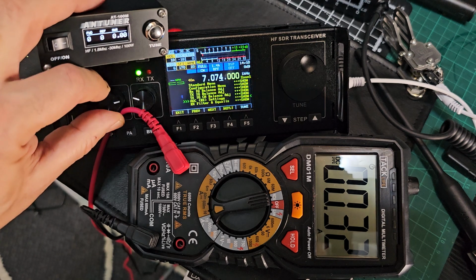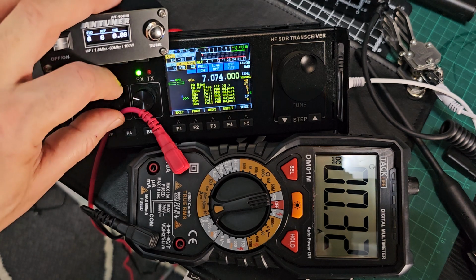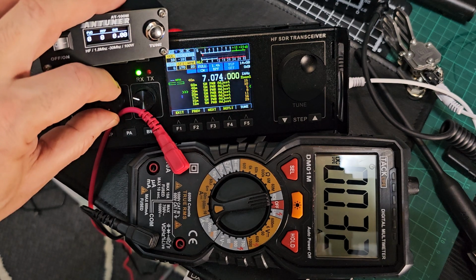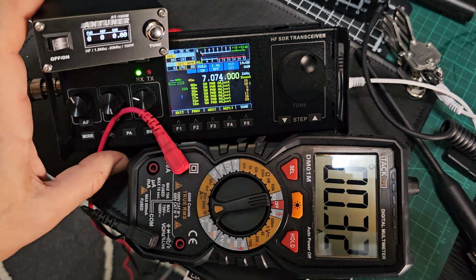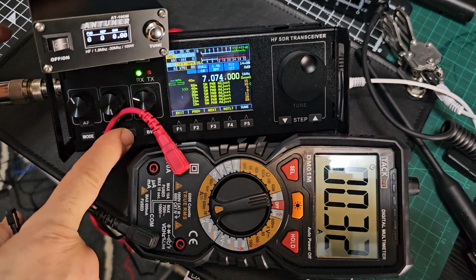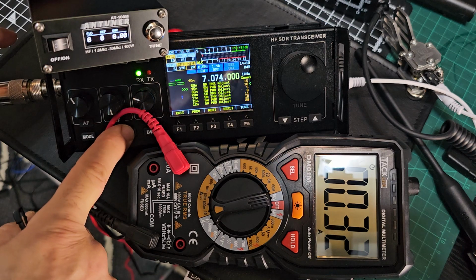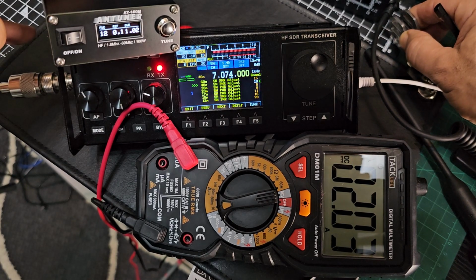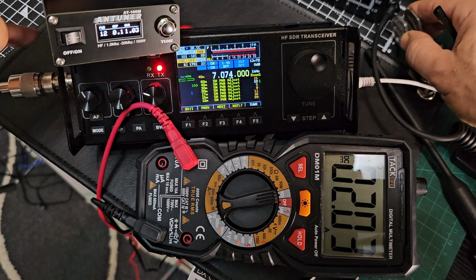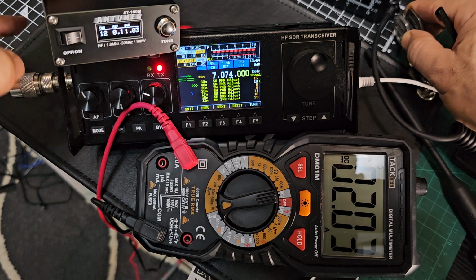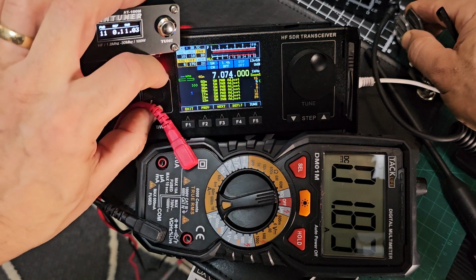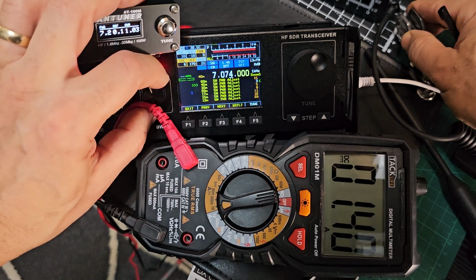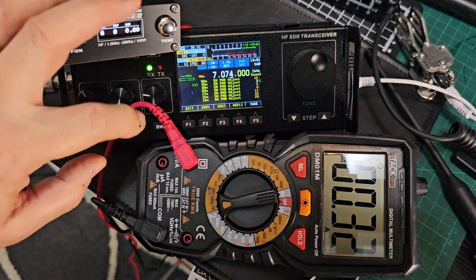Full power, where's the 5 watt one gone? There it is there, 5 watt, 40 meters. Change the power, press the PA button till it says 5. We'll key again. 40 meters, 5 watt. Look, that's way up. So you could lower that. So that's what they say about these radios. There is setup to do, otherwise it will overheat basically. And you save the setting by exiting.